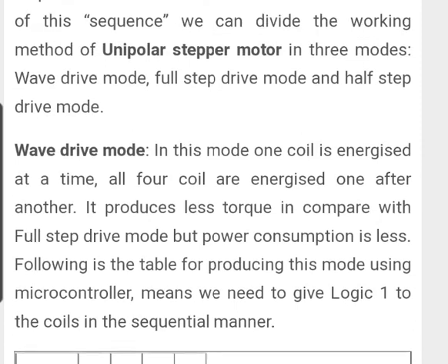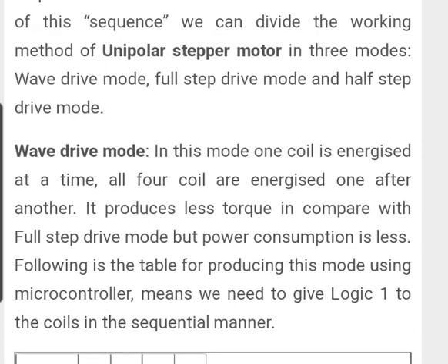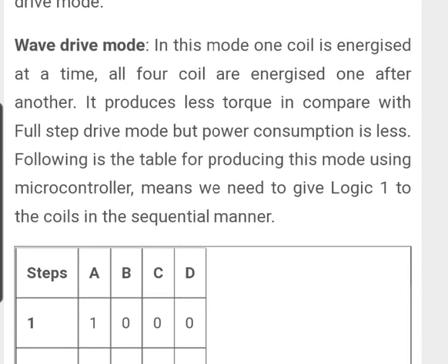Then wave drive mode means what? In this mode, one coil is energized at a time and all 4 coils are energized one after another. So it produces less torque in comparison with full step drive mode, but the power consumption is less.